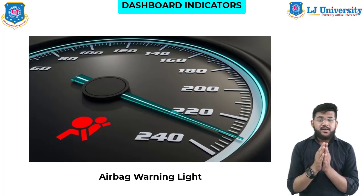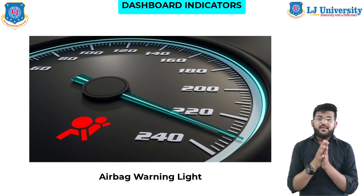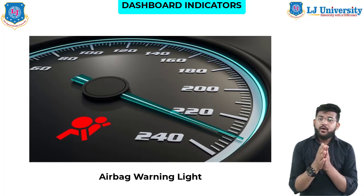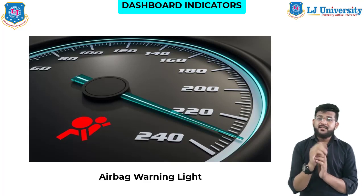In such a case there might not be any issue with the airbag itself. Sometimes the airbag ECU must be cleared to shut off the warning light. You can remove the airbag ECU and send it to the company to clear it for you. You should not ignore this airbag light, as the airbag will not deploy in the case of any major accident and it can lead to severe injuries. This was about the airbag warning light.